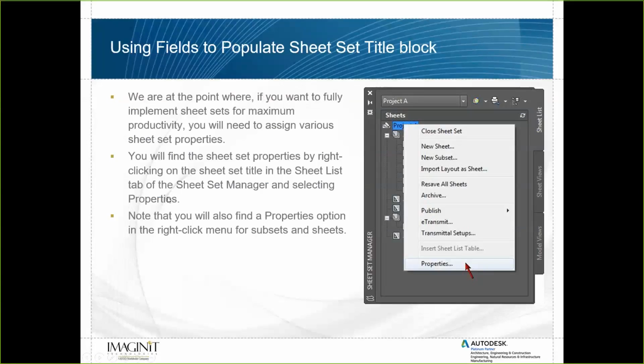Okay, so now we've created our first sheet set. So now we want to use the power of those fields, right? These are the fun things that we want to use. So now we're at the point where we fully want to implement sheet sets for maximum productivity. Now we need to create and assign various sheet set properties.